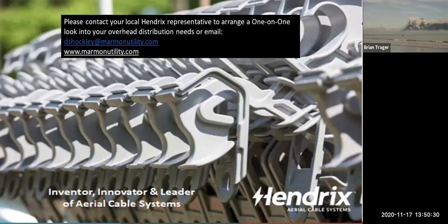Okay, very good question. So the first thing I have to say is National Electric Safety Code says that if there's not a concentric neutral on it, it must be treated as bare wire for all safety and work methods. So their MAD, their minimum approach distance, cannot change. So how are they going to work it with work methods? Basically, with some modifications, while still respecting National Electric Safety Code Rule 230D, and while respecting 100% of the safety and work method regulations of their individual utilities.